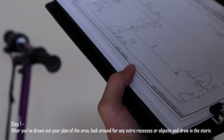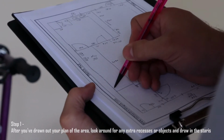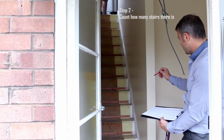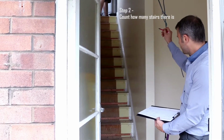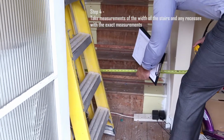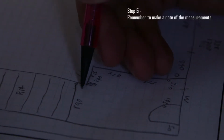Next, sketch out your stairs. You don't need to draw the handrails and all the detail, just a simple light line to indicate. Count how many risers there are. Risers are the times you step up. Clearly state the risers with an R and the number. Measure the width between the walls of the stairs. Measure a clear starting point for the stairs.